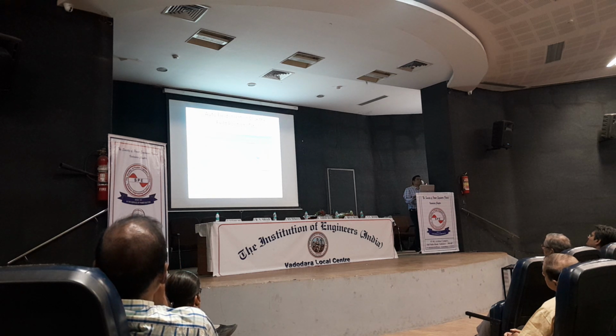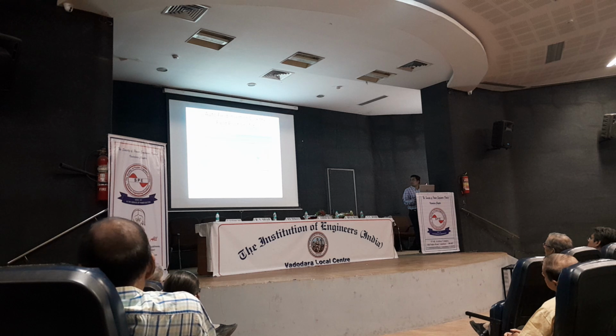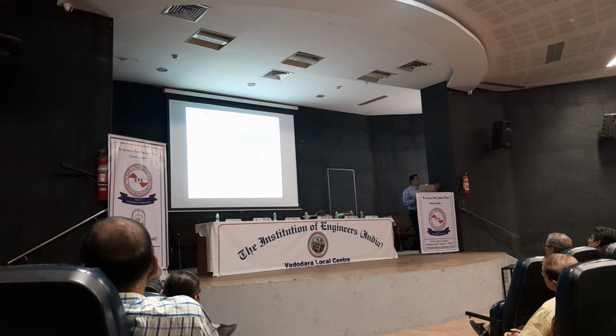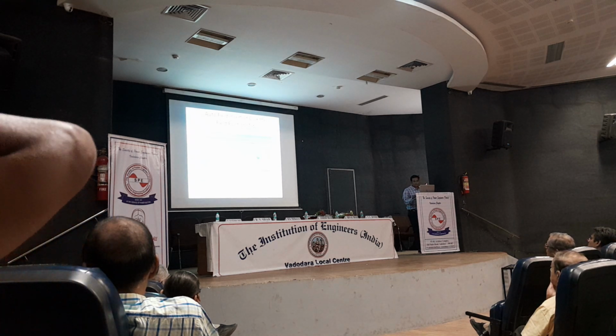Now, I told you that there are two ways to display the information. One is field value, one is the pie chart. So if you want to add multiple field values, you have to use this default drawing values for new objects, so that you can place various information next to the bus. One is megawatt, active power flow, reactive power flow, active power losses, reactive power losses. You can display at both the sides, because you have multiple components. For each and every component, you have to select which values you want to display, and for display, these are the ways you have to follow to get the information.